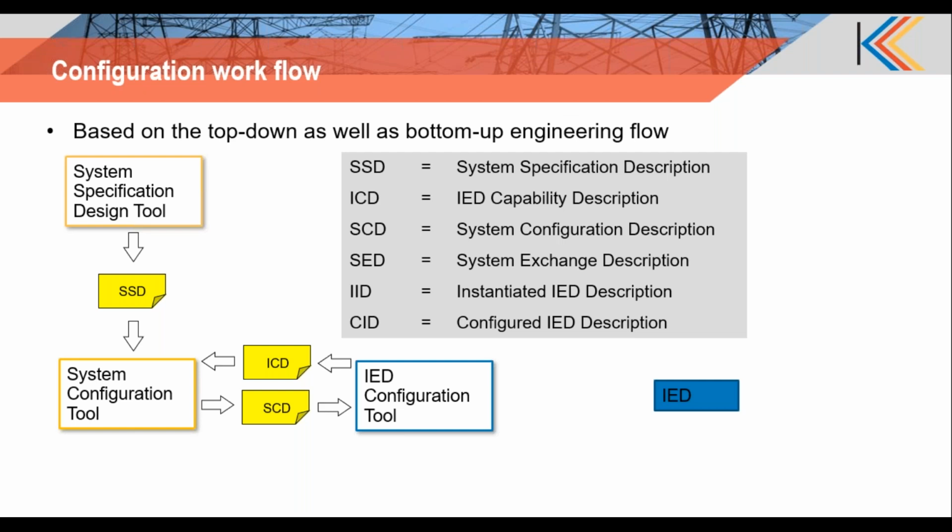But like I mentioned, the ICD being a generic file, in most cases the ICDs will be predefined. But as part of the project, the IED configuration tool may make some modifications in the IED's data model. It may enable one of the logical nodes or one of the functions that was previously disabled. The IED configuration tool always has that flexibility, and those modifications get downloaded into the IED. But the problem is that all those additions will not travel all the way back to your system configuration tool.